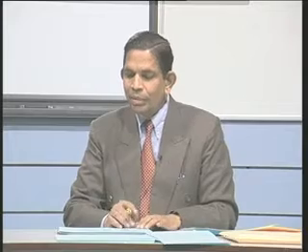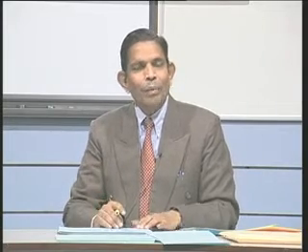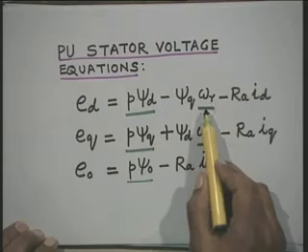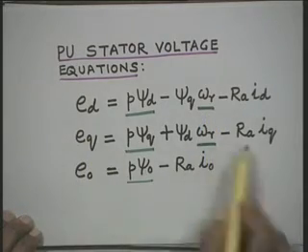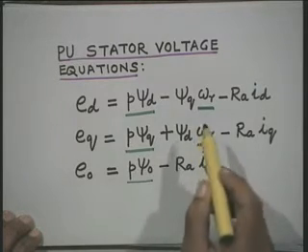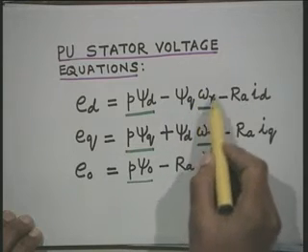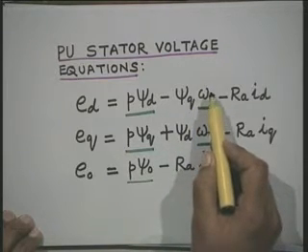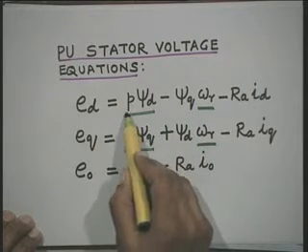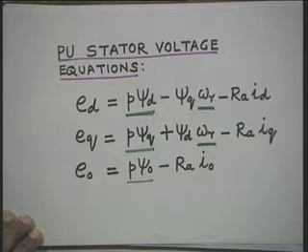That is, in the per unit system we make omega r equal to 1. This is another assumption. Now, in practice, by making omega r equal to 1, there is not much simplification in the system model. However, the very interesting thing is that if you assume omega r equal to 1, then this assumption to some extent counterbalances the assumption where you neglect the stator circuit transients.